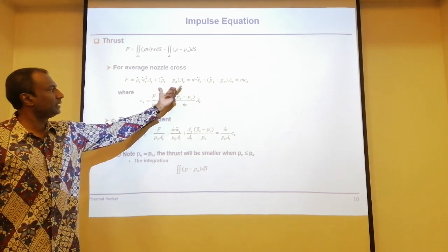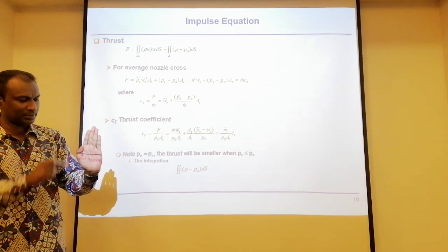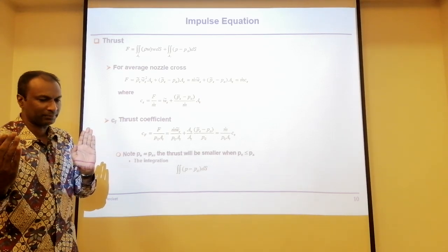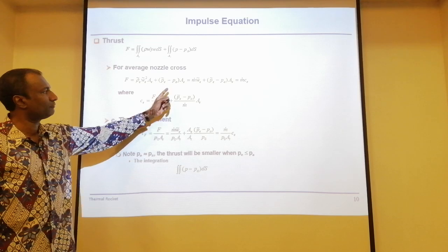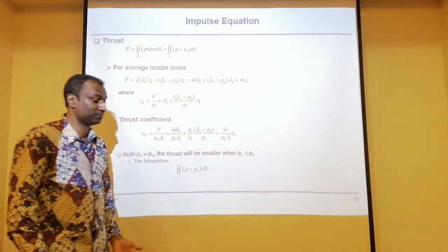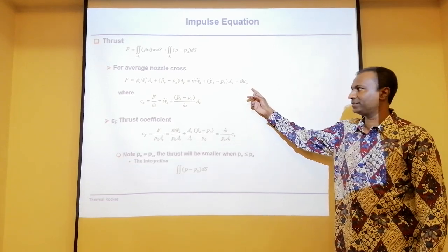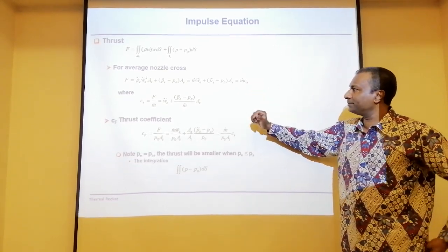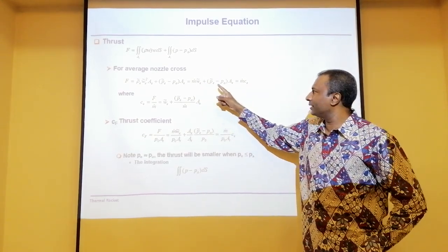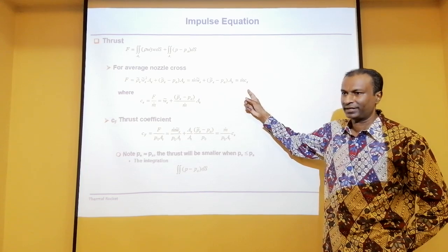Okay, and the atmospheric pressure. So at the exit of the gas, there will be a very high amount of pressure actually. Then you have an atmospheric pressure. So this is important basically in order for us to give you the thrust. Now, what this is equivalent to, technically speaking, this is supposed to be equivalent to the mass flow and the effective exit velocity. Okay. Now, look at this. This is what is happening, and this is supposed to be equivalent to a corrected effective exit velocity actually.